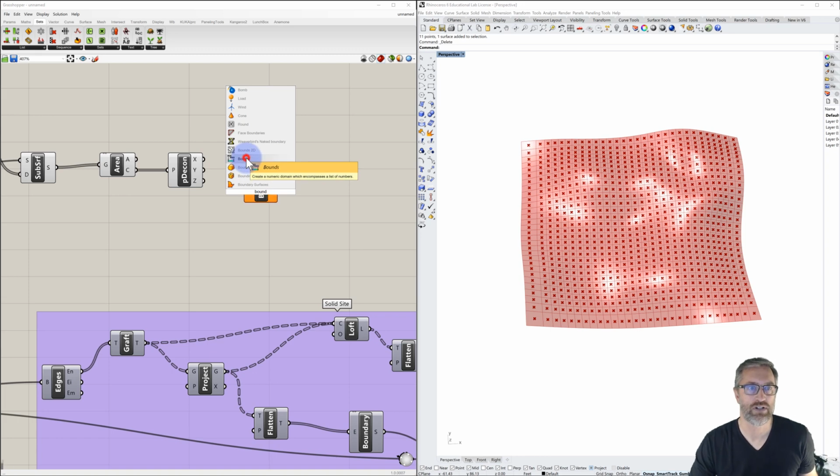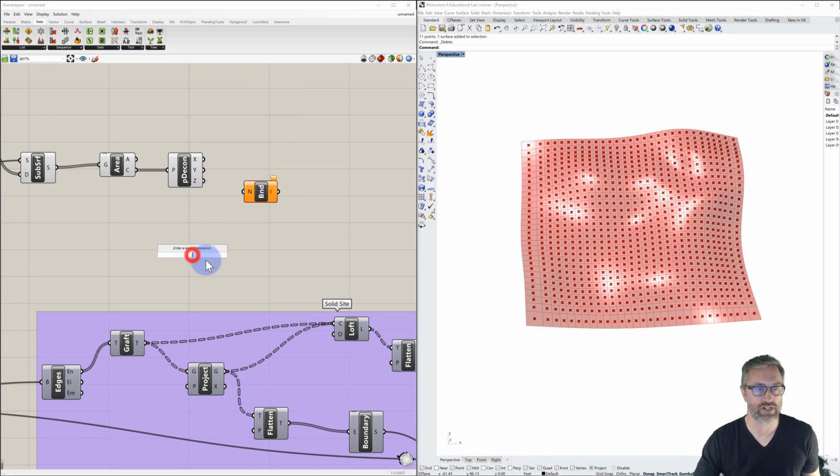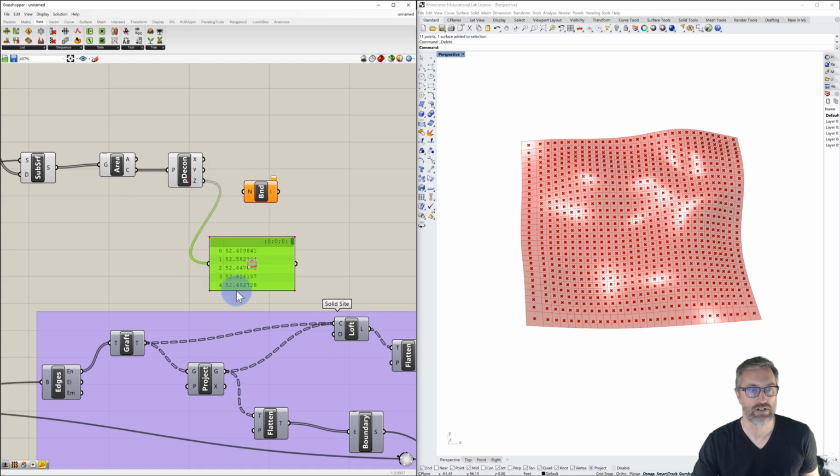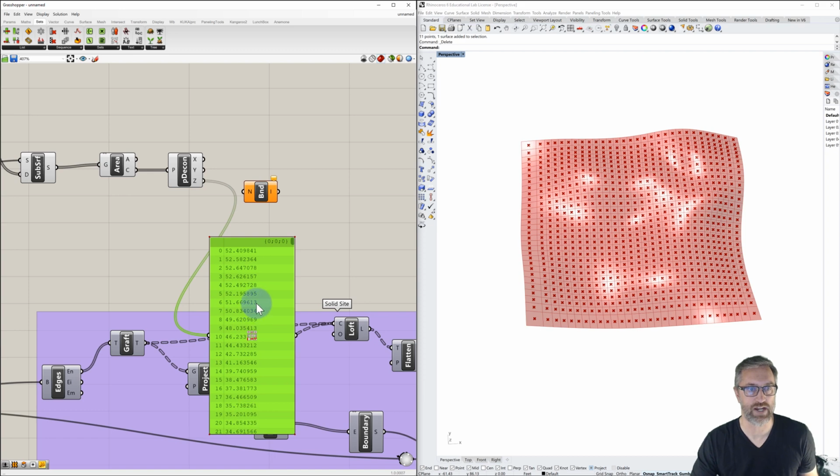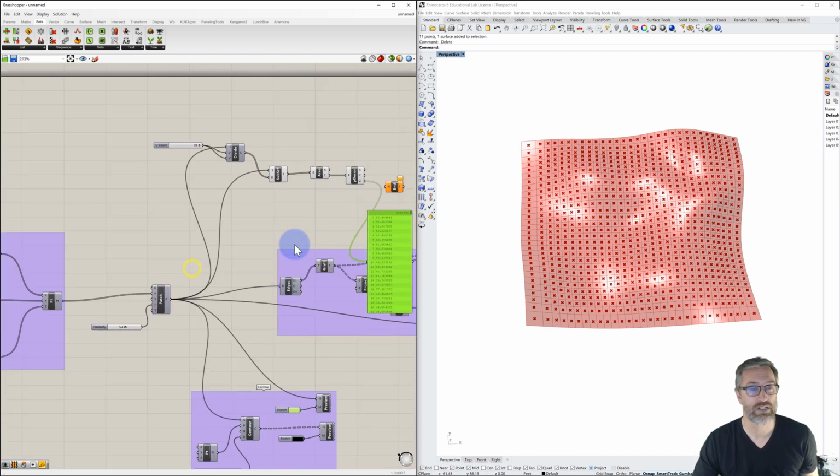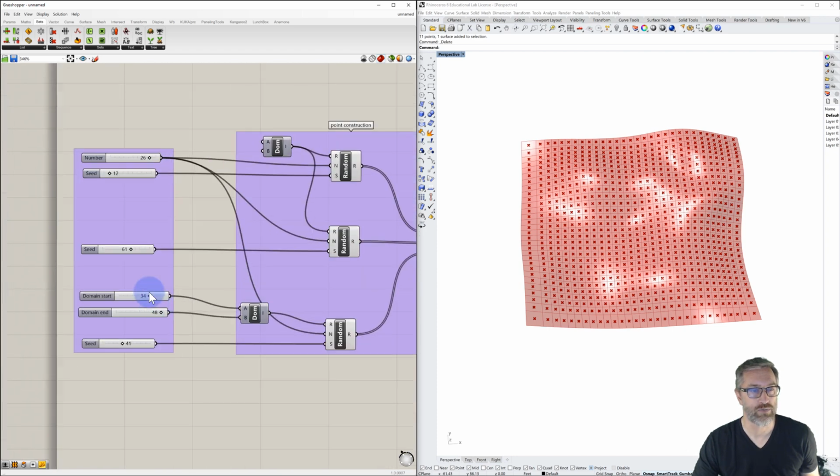And so bounds, so I'll bring up some panels again so you can see what we're doing. Panel. And so the Z values that are coming out of those deconstructed points are really just a list of values. And these are their heights. Remember, these heights should correspond to what our domain was within here, but again, I saw some values that were greater than 50.